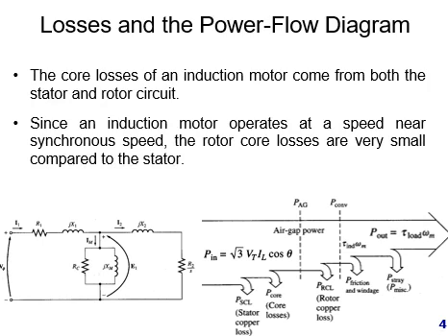The core losses of an induction motor come from both the stator and rotor circuit. Since an induction motor operates at a speed near the synchronous speed, the rotor core losses are very small compared to the stator.